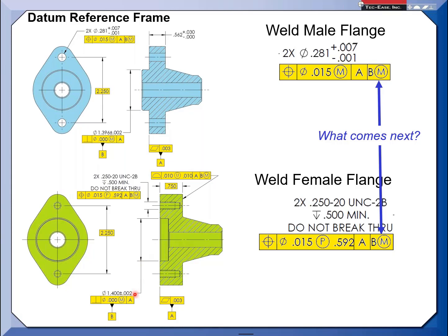So in other words, what's happening here is that if the datum features depart from their MMC size and go towards LMC, there's going to be a little bit of clearance between these two mating features. Then we can allow these features to take advantage of what we call additional shift. So if the features go from MMC to LMC, a little bit bigger, I can allow a little bit of movement, shift. So you see the end solution of what we're looking for here.